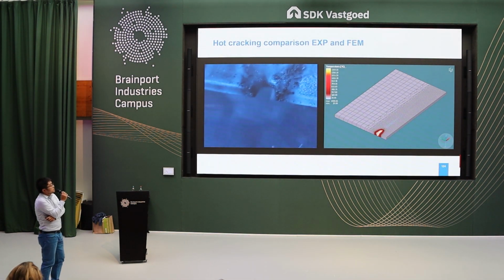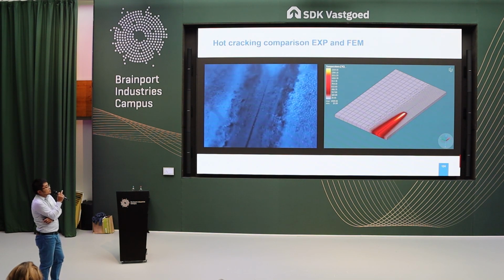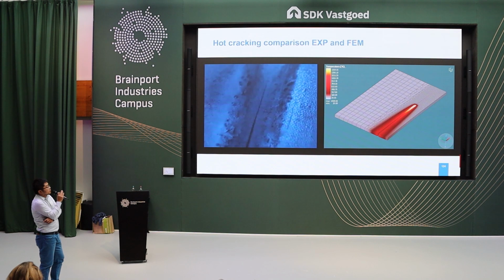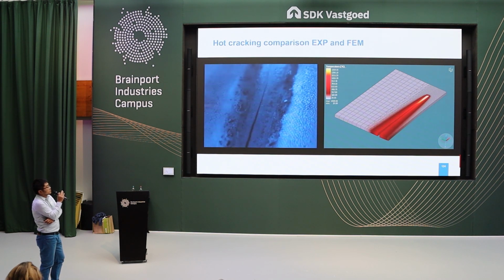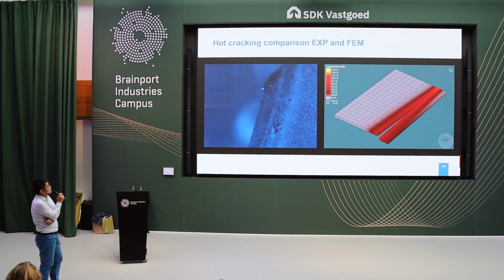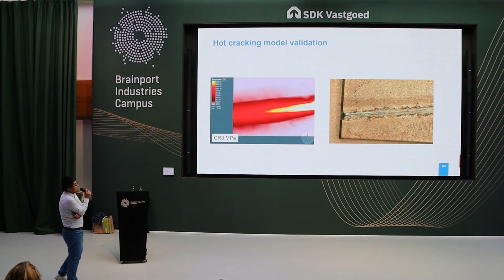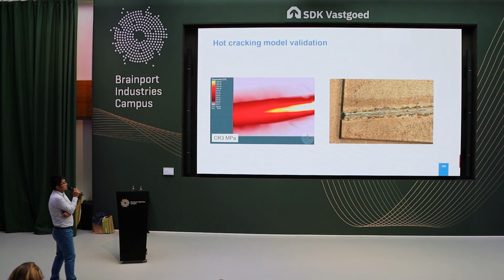Now we come back to this video again, and it makes more sense to see that we can very well represent this hot cracking during the laser welding process. In addition, to compare with the experimental measurement, we compare the length of the crack, and we determine that for this DP800, the intrinsic property for the weld strength in the weld mushy zone is criterion 3.